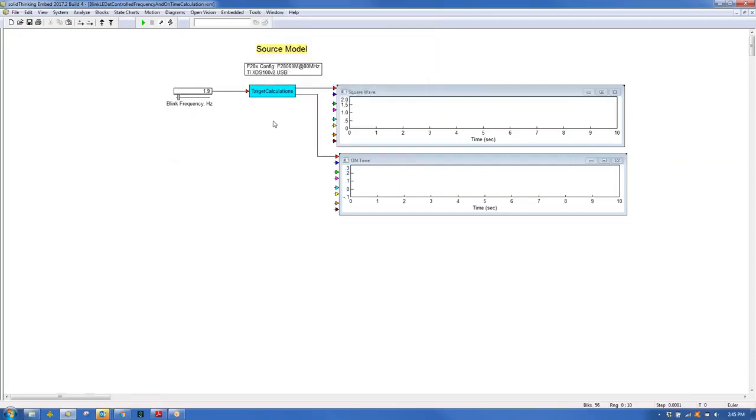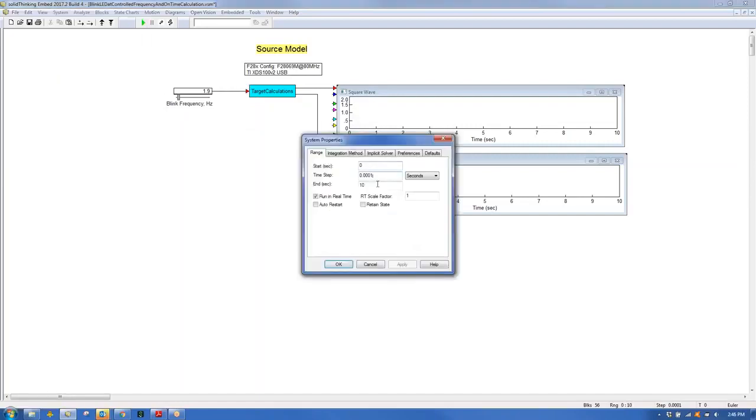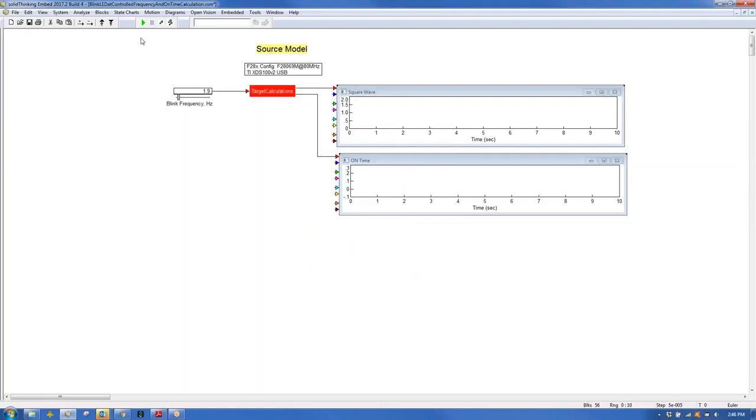So now I can make changes. Let's say that I wanted to change the source model somehow. Let's just say I wanted to run it faster, the source model. So let me go in and change this to 20 kilohertz. So I'll make it 0.00005 seconds, which in kilohertz is 20 kilohertz. Okay, I will generate code.